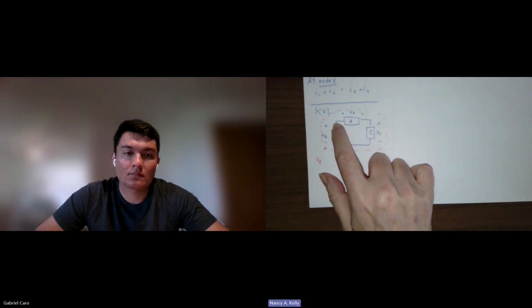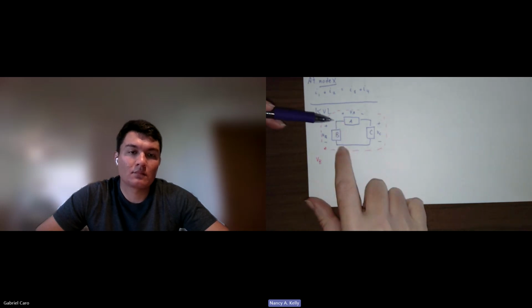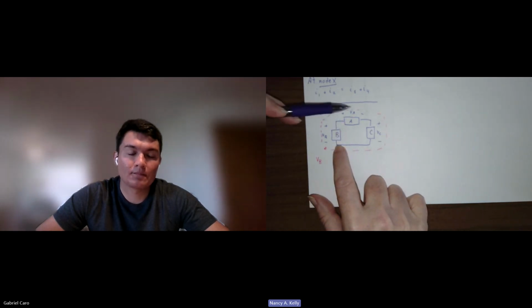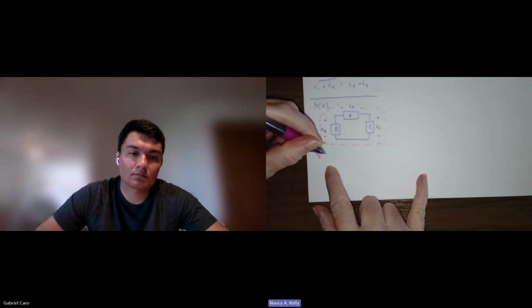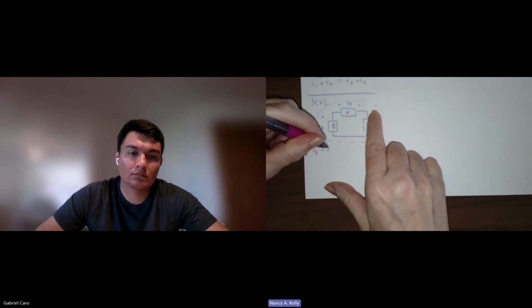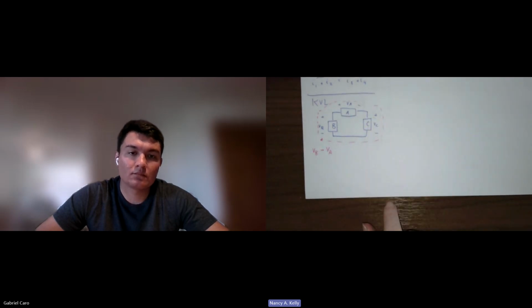And so we don't worry about what's going on along the wire. Then we come to this one and you say, okay, now I'm at VB volts above the reference point down here. Then when I pass through this element, I drop my VA volts because I start at the plus terminal and I go to the minus terminal, okay? So that means I'm going to express that change, moving me over here, as minus V sub A, okay?